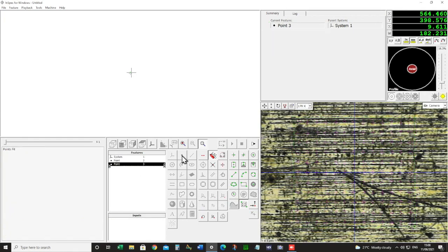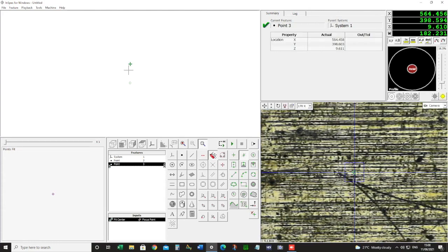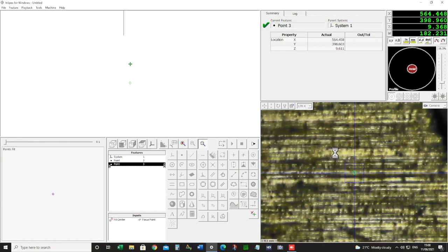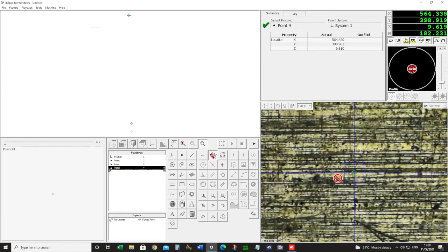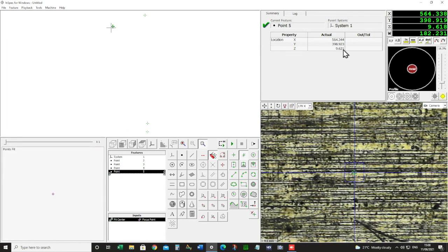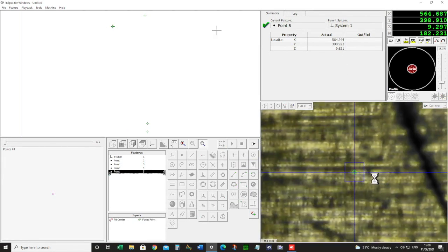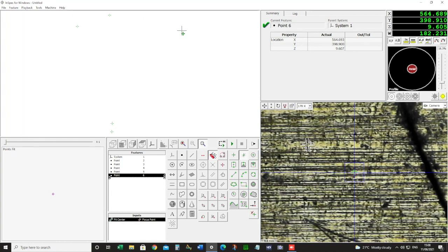and we go back to doing our other point, we'll do another point on top of that. We're now looking at a difference of only 3 microns, but if we try and find somewhere else, there's another micron difference. So if you're chasing tight tolerances, there's a higher one. Look at 9.621. This could be quite important, especially when you've got surfaces that have tooling marks. Now we've got a 9.607, so between those we've gone 14, 15, 16 microns.